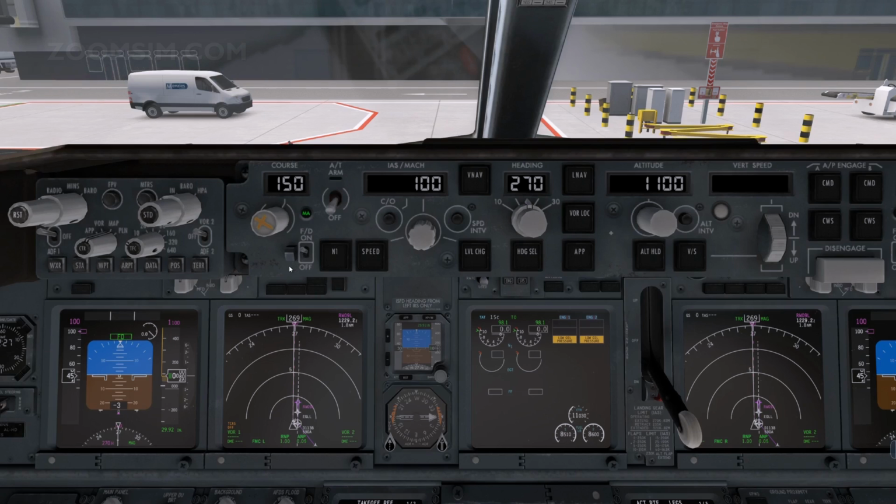Move the switch for the pilot flying to on first. The flight director computes and displays the required pitch and bank angles for a selected flight path. Bank angle as required. Autopilot disengage bar up. Nose wheel steering. Guard closed.